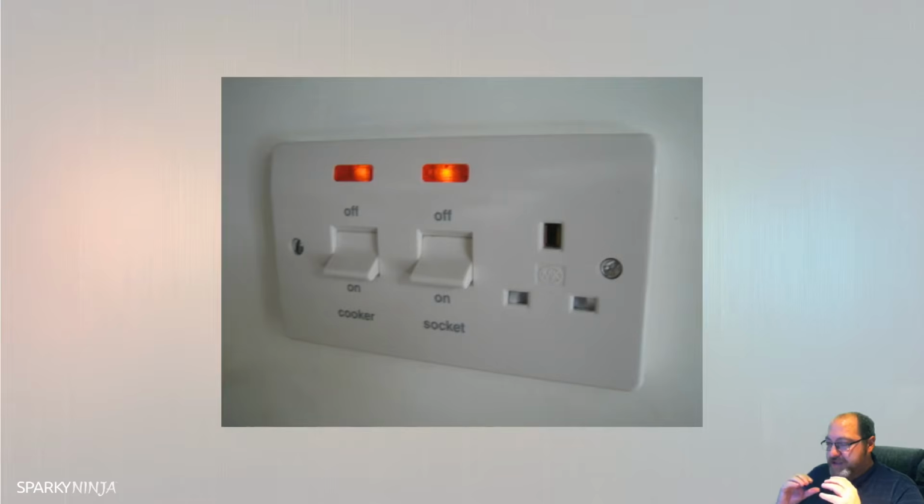a mechanical maintenance device just needs to be identifiable. So you have an off and an on, or you have a light that goes off and on. Ideally, if the circumstances due to risk assessment say you should lock it off, you would lock it off. We're going to see all this covered more in 537 anyway, but right now, means of mechanical maintenance.